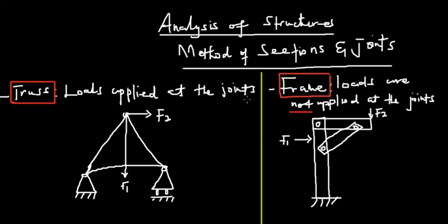Okay, right, so it's in two portions. We will look at the method of sections and then the method of joints. The method of sections is when you have a structure but there is a cut, a break within that same structure. So you tend to find the forces whenever there is a break or a section being cut. And then we have joints. Joints is where we mostly concentrate on the portions of the structure that hold the entire body of the structure together. That gives it strength.